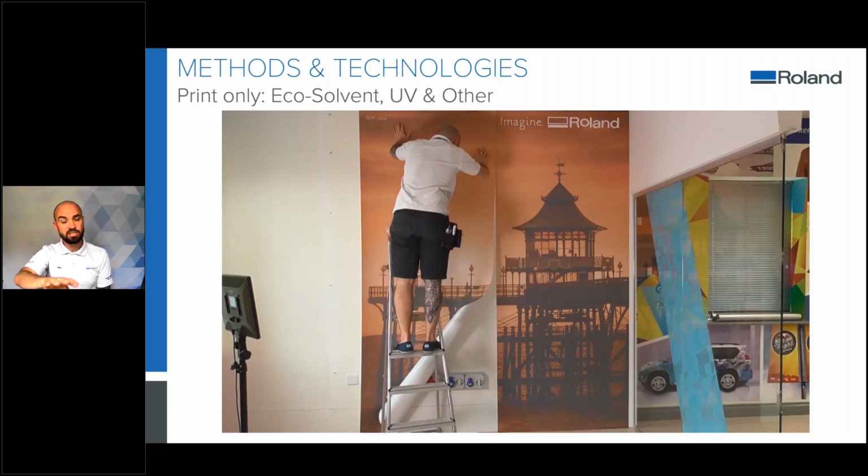So what I needed to do here was lay 1 tile and then again reveal the top section of the next tile to hold that one in place. And again, this would have been a lot easier with 2 people, so you can have somebody at the bottom half of the tile to align any elements of the graphic that you can. So you can see here the top part of the graphic is just a nice sky blend, so it was a little bit more tricky to align at the top there.